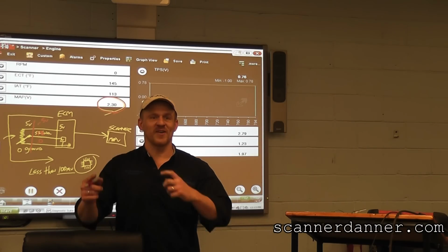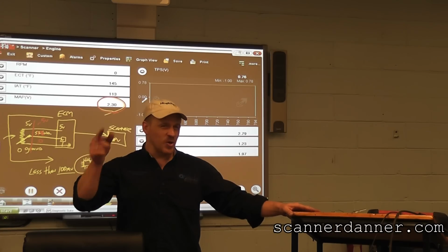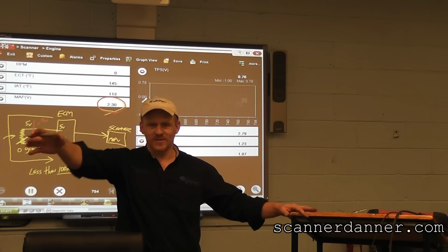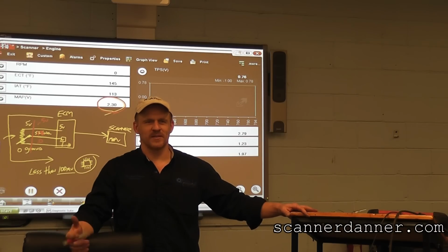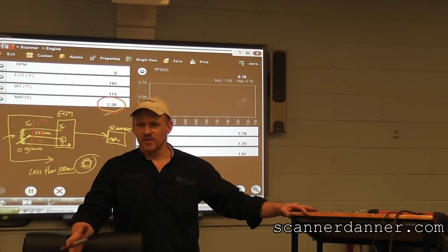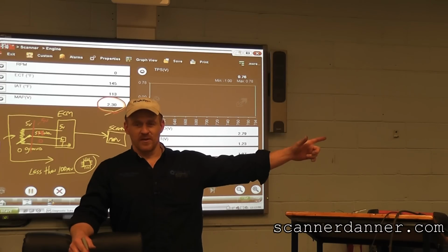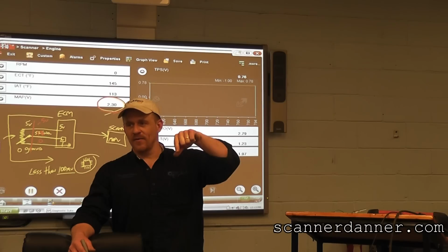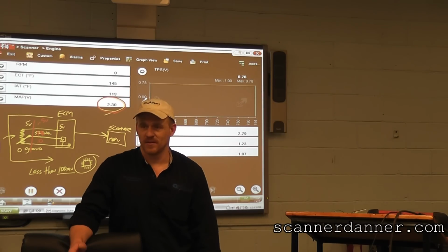And then somewhere in there, Tom's like, I saw the TPS move and I heard O2 the first time you said it, not TPS. Totally disregarded him, but he was right spot on. That makes sense where we are? Mm-hmm. All right, so a couple lessons here. You see voltage live that doesn't match scan data. You have a wiring or computer problem in most circumstances.